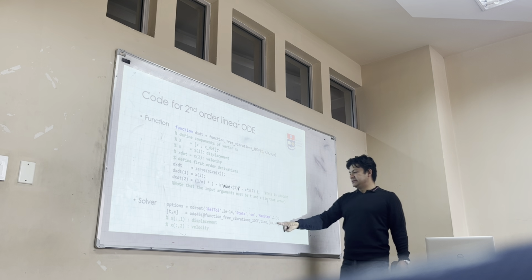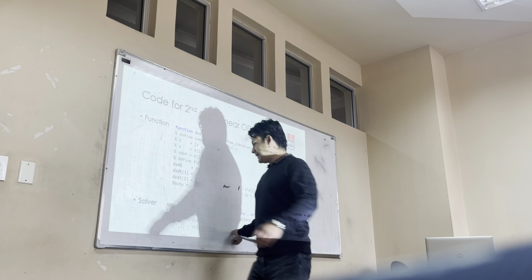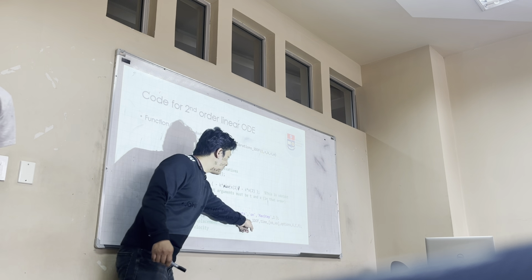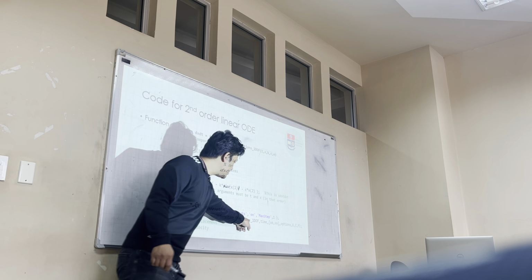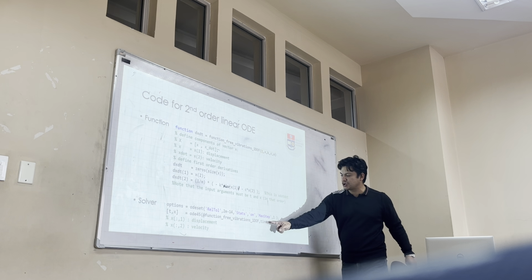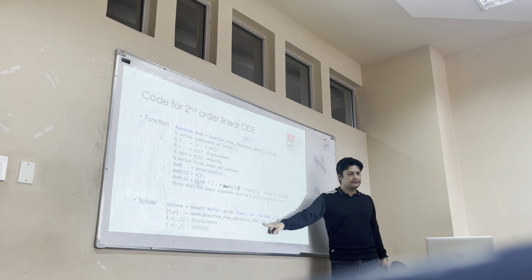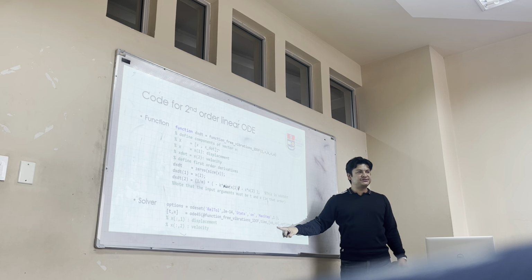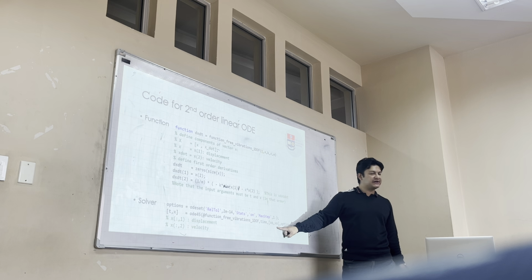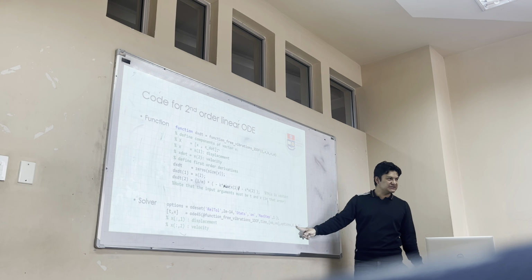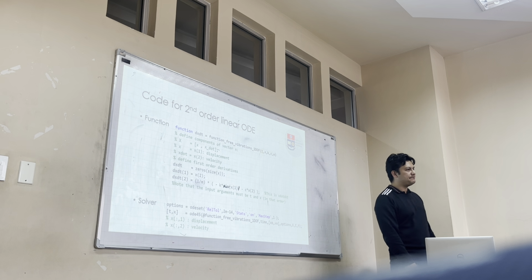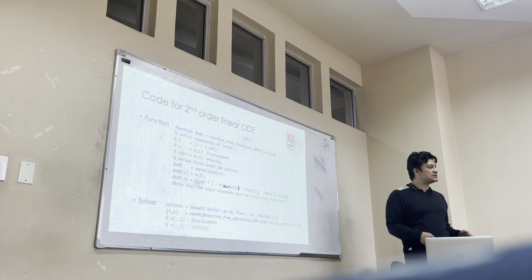And here is the code. Here, we are calling the function that we just defined previously. Right? ODE45, we call the function. Time is a vector of time that has to be defined. This x here gives you the initial values or the boundary condition, x0, velocity 0. Right? You call the options that you just defined there, and you put the corresponding value of k, the corresponding value of c, the corresponding value of m. Click play, and you get the solution right away.